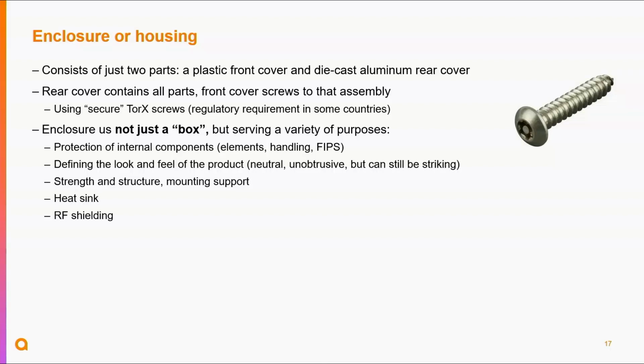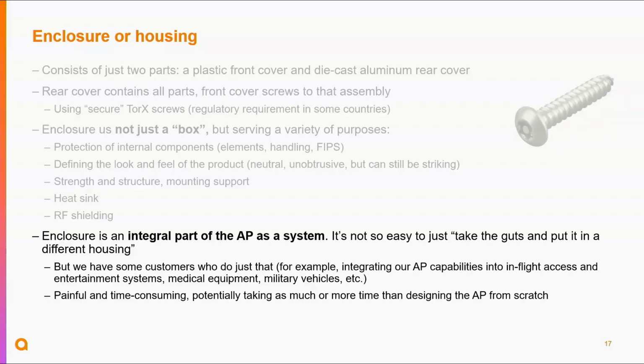It protects the internal components. It, of course, defines the look and feel of the product. It gives strength and also supports mounting, of course, the AP. It also serves as a heat sink. We talked about touch temperature already. The back of the AP is a massive heat sink. And it also provides additional RF shielding for the components on the board. Yeah, as I said, integral part.